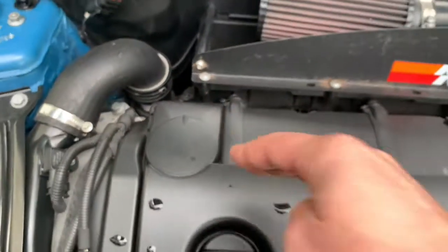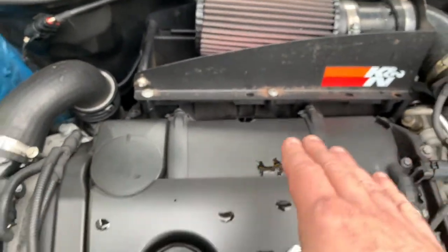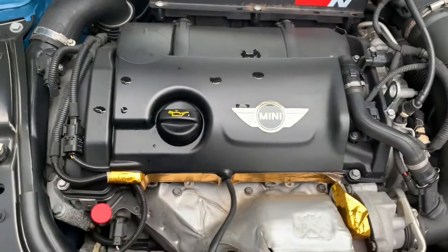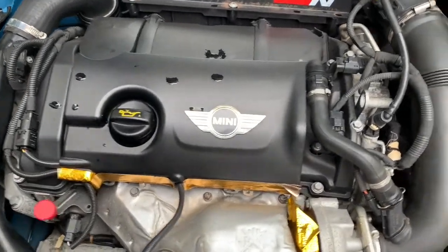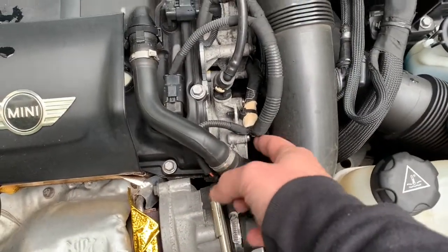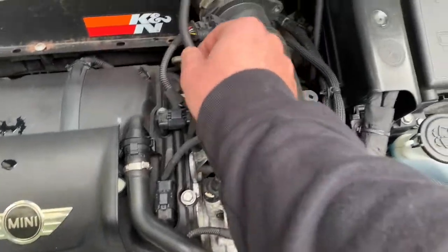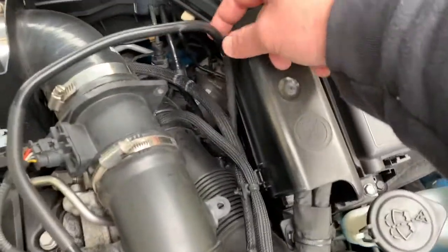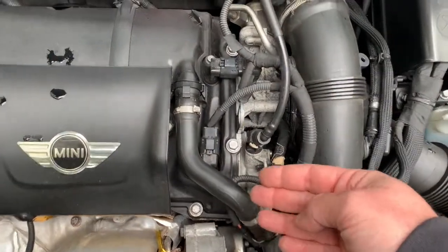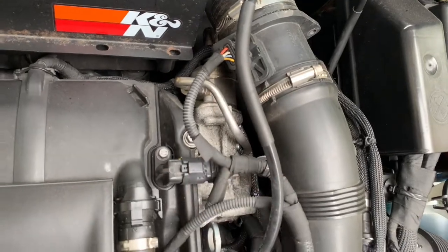So both the intake cam in the back and the exhaust cam in the front are variable on this car. On this, the exhaust cam here, remember that the exhaust is on the turbo side. This is my feed line to my brake booster, so it also has a cam-driven vacuum pump. And then on the intake side, that's where they put the high-pressure fuel pump on this.